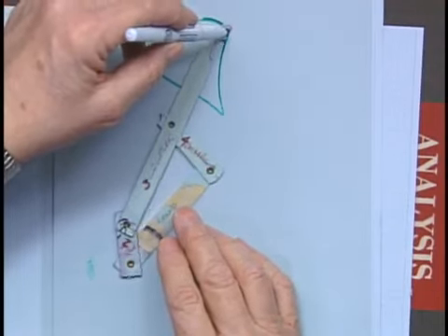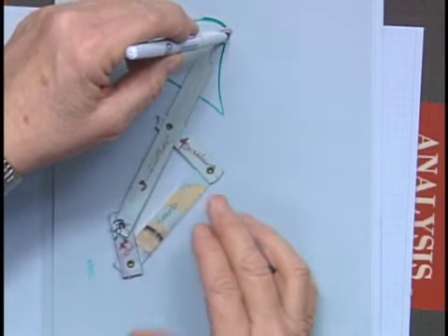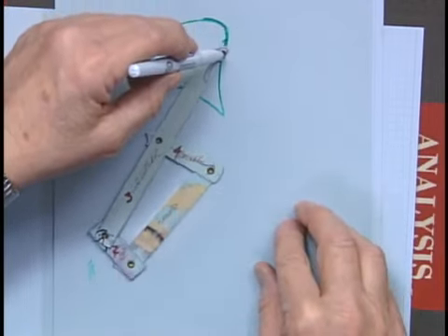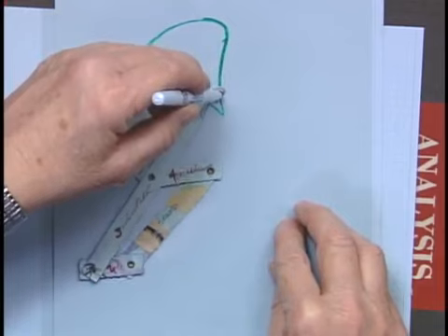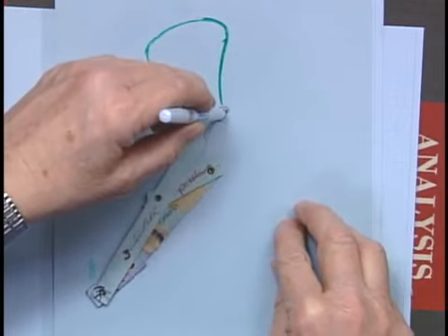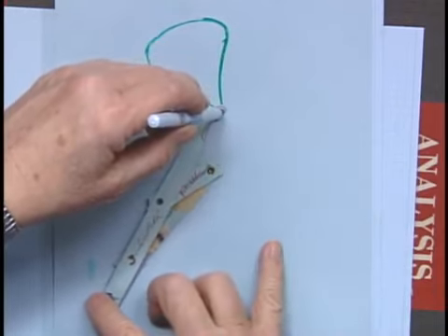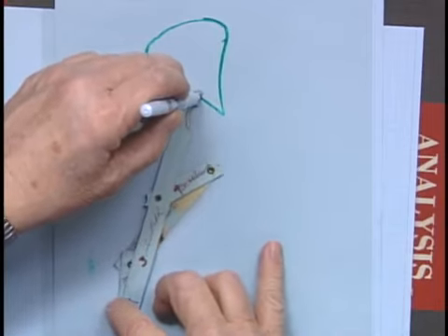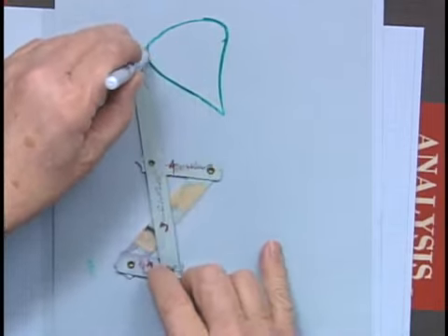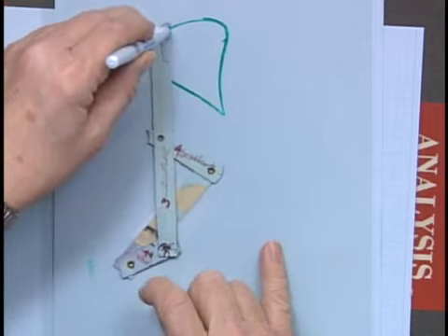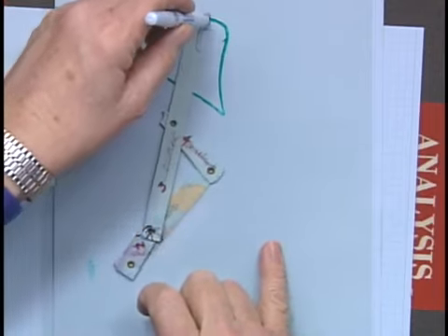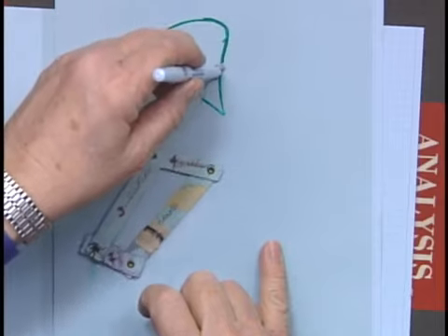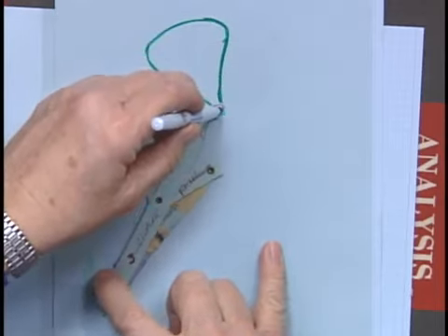I'm going to pick up on the film again and pull it down. The shutter's closed, the screen is black, you can't see what's going on if you're in the theater. Now I'm down at the bottom here, and the shutter's now opening, so you can see the next image on the screen. I'm coming around the backstroke, wasting time. Shutter's closing, screen's gone black, I pull the film down again. And that should give you some idea of how this works.